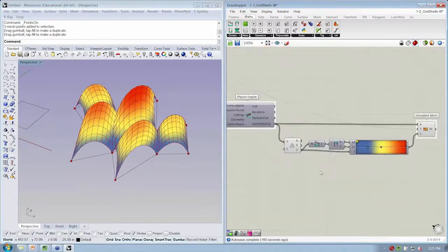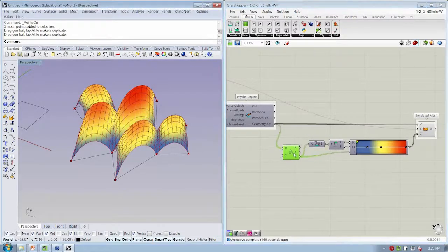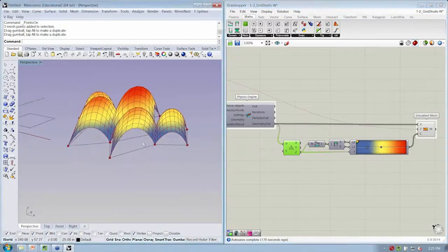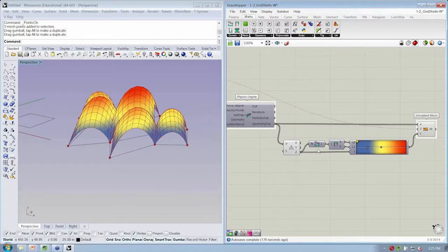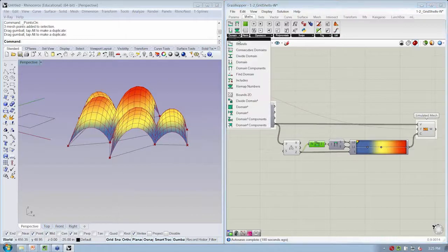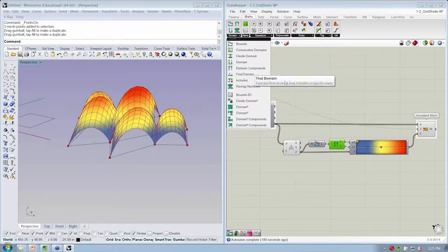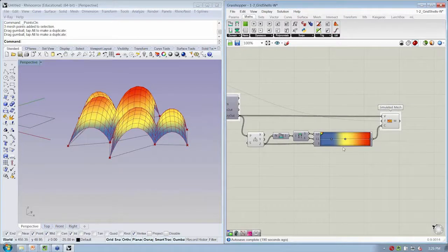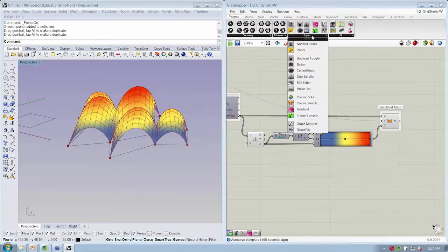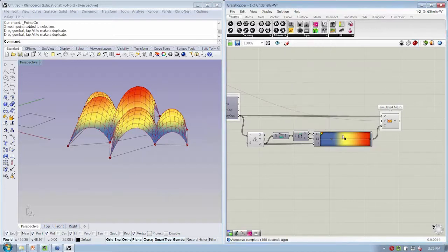There's a question about reviewing the color gradient. So what we did is we took the geometry out, which are our points that have been simulated, so they're up in space in the z direction, decomposed them with the point xyz, found the minimum and maximum from math domain bounds of all those values, took the domain apart to get the start and end by domain components, used a color gradient object from params input gradient, and you can specify just one of the defaults for starters.